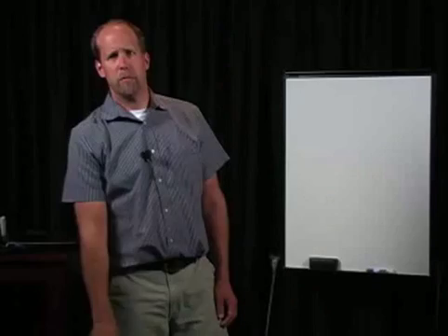Hidden areas. Special attention should be given to areas that are hidden and that might have gotten wet. Areas behind walls and in ceilings and crawl spaces in attics are frequently overlooked by building occupants and not dried carefully. In general, all wet areas should be completely dried within 48 hours to prevent mold from seriously growing. Routine maintenance is important. A number of items frequently involved in mold problems should be checked and maintained routinely.